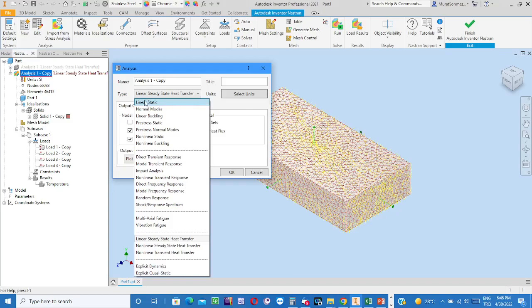If you don't know whether the material object will stay in the elastic region or exit it and reach the plastic region, then in the first trial you may select linear static. Or if there is a doubt that probably the yield limit will be exceeded, then at the beginning select non-linear static option. Okay.